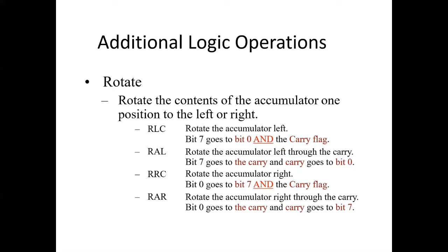Next is RAL. RAL stands for rotate accumulator left involving carry flag in rotation. It rotates the accumulator contents to the left by 1 bit position. After rotate left operation, the bit that moves out from the MS bit position goes to the carry flag. And in this process, it also moves the earlier carry bit to the vacancy created in the LS bit position.